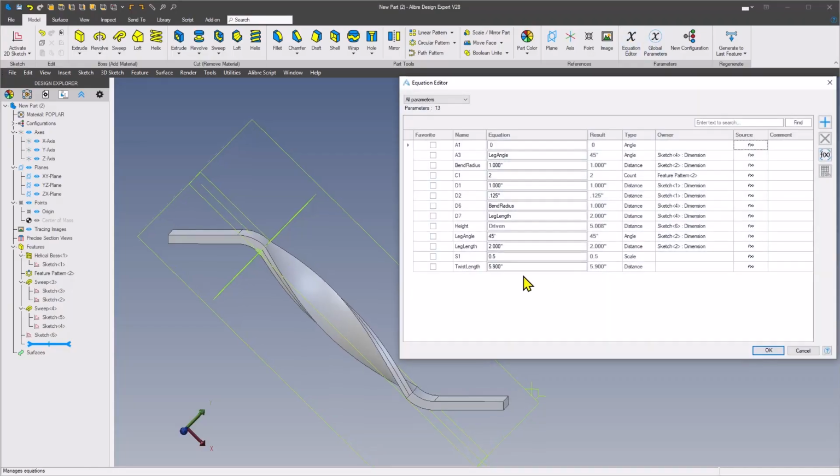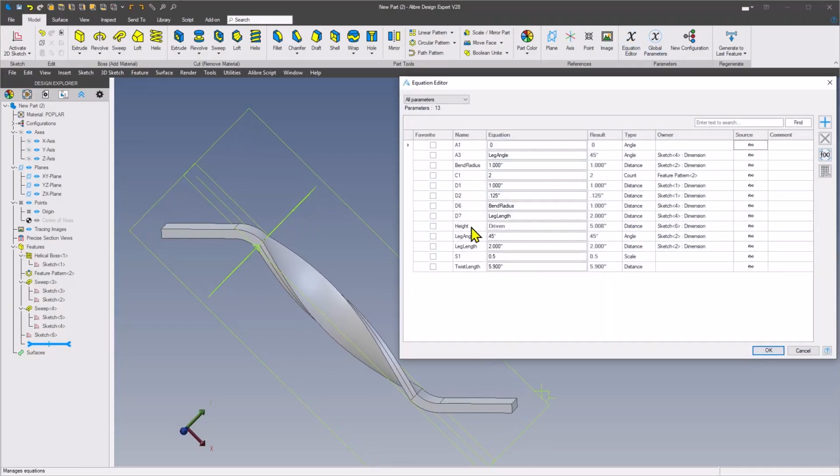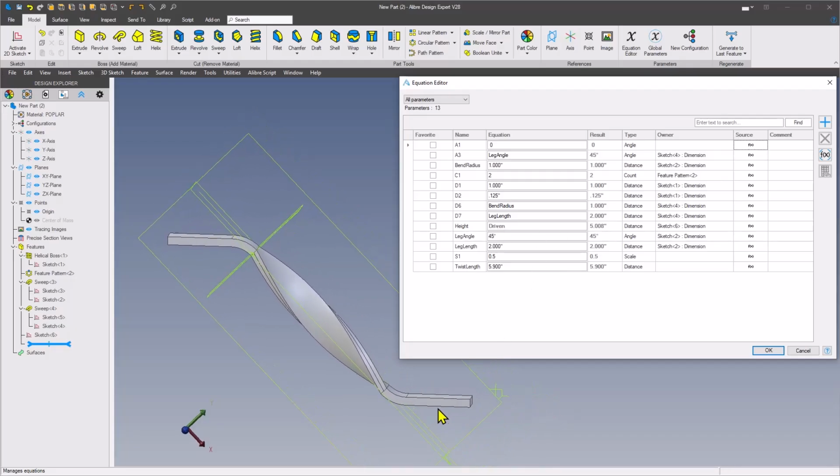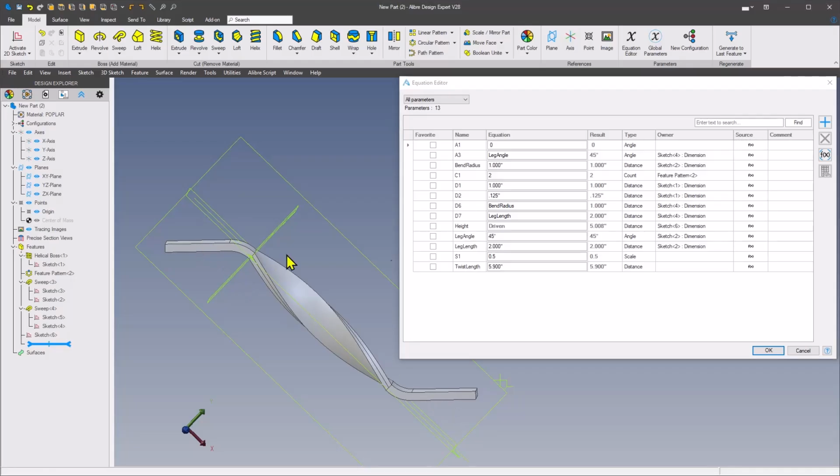And through a few steps, now we're at 5.9, and our driven length is 4.008. So as far as tolerance is concerned, we're probably right on the money for the height from this face normal to that face. So that gives you parameters that you can use for adjusting the height.